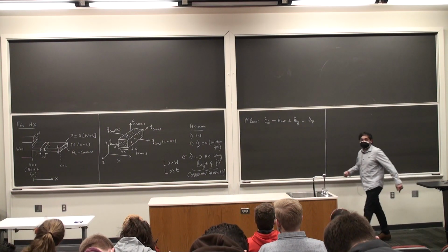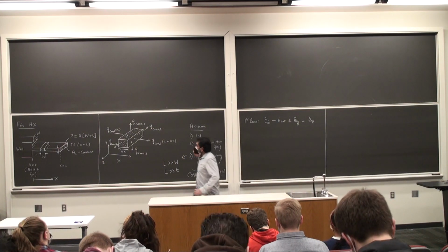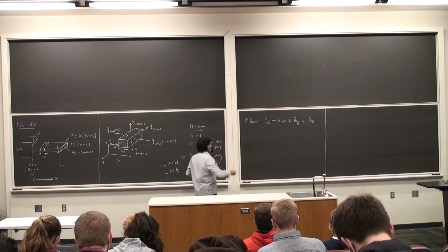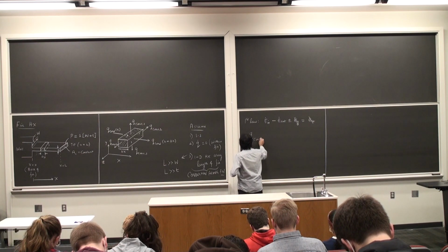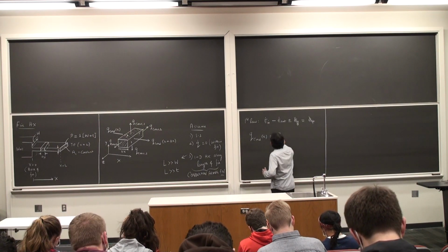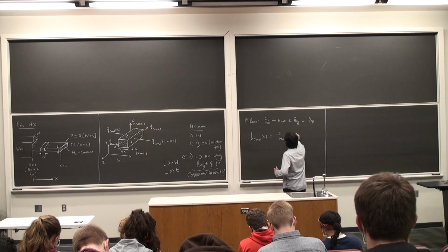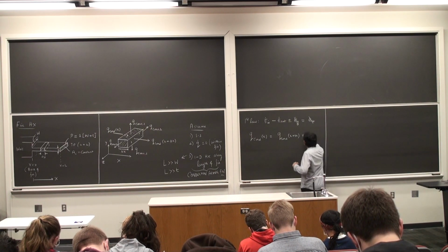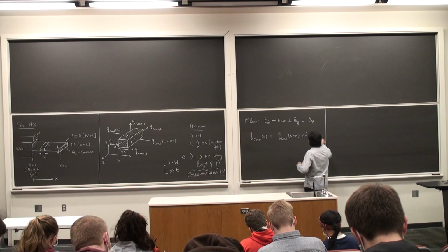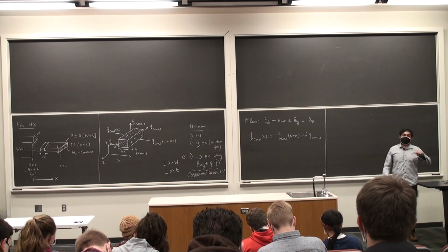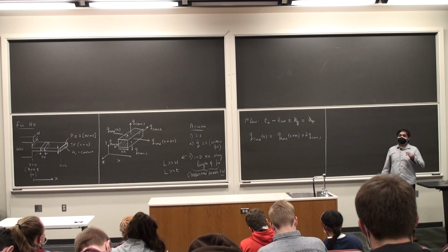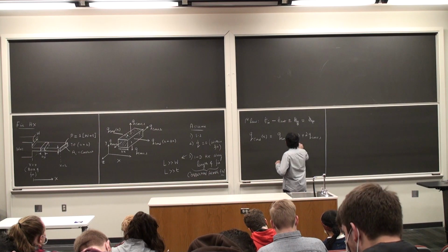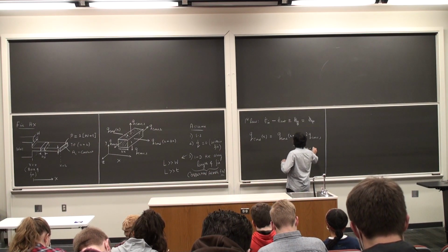So from here, for E dot in and E dot out, I have Q conduction coming in, and then I have Q conduction going out. I have convection in all the four orthogonal directions in the conduction transfer. So I have Q conduction x is Q conduction x plus delta x, and then I'm going to have 2 times Q convection 1. Notice I'm looking at rate of heat transfer, not fluxes yet. I have not put the double primes. If I put the double prime, that's a flux. And then I'm going to have 2 times Q convection 2.